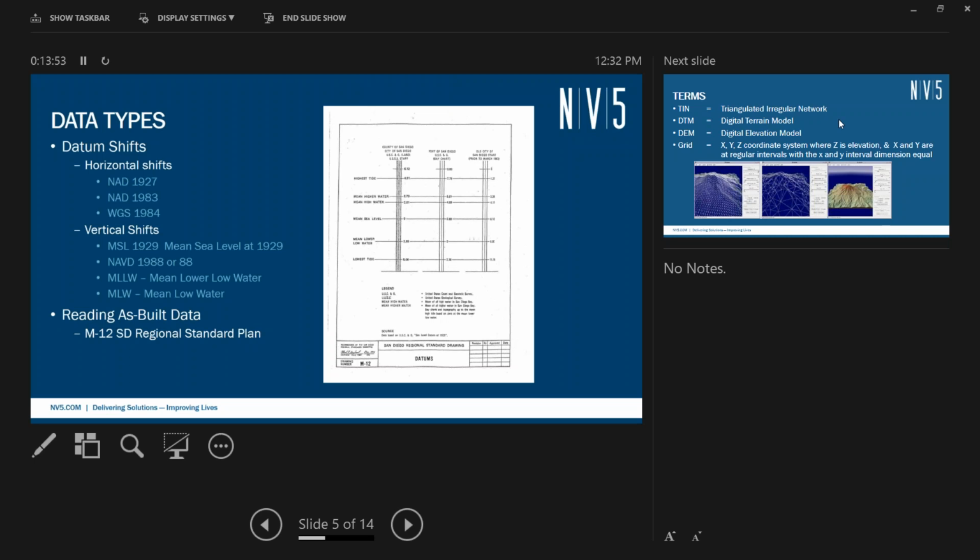If you say, hey, I'm really doing a street rehabilitation project, I'd really appreciate it if you could shorten up the cross section survey shots. Instead of every 25 feet, do every 15 feet down the road. Give me a cross section. That's what I need on this project, because it's really flat. I need to make sure that the elevations are true and I'm tying in and it can really feather in everything. Okay. So be in communication with your surveyors.